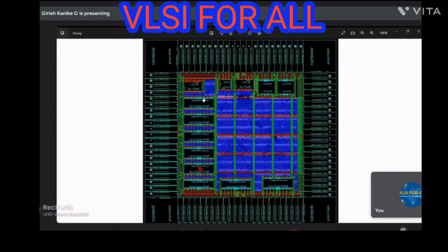The fourth and fifth were for clock tree synthesis, CTS, where you provide the clock lines. And the fifth and sixth were for power, the PG rails, whatever I said about power planning. The fifth and sixth VDD and VSS were drawn on the fifth and sixth metal layers. These macros and standard cells will tap the power from the fifth and sixth metal layers. Some standard cells, not all; for particular standard cells, metal layer 2 provides the power.